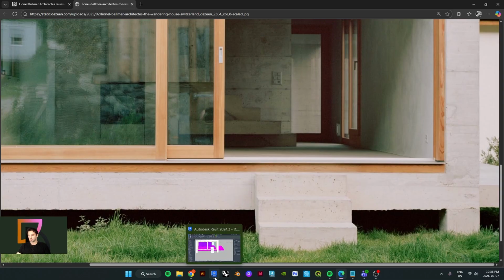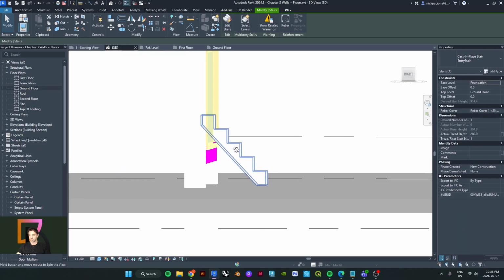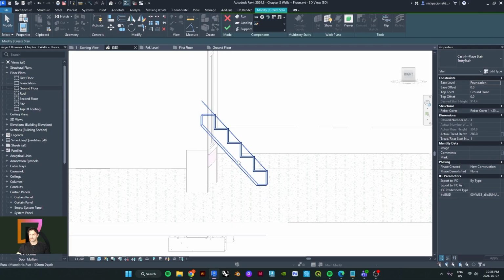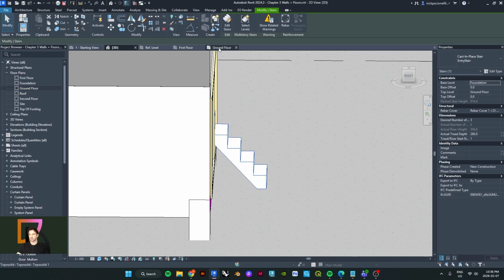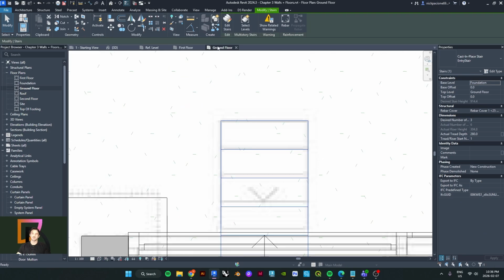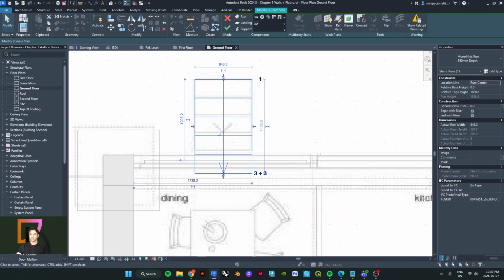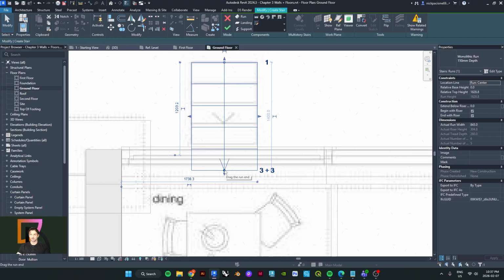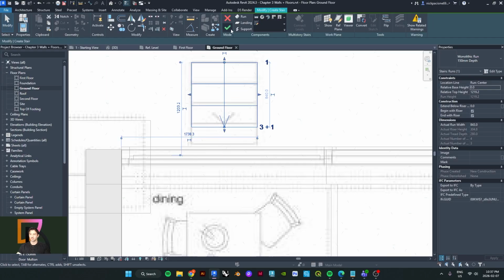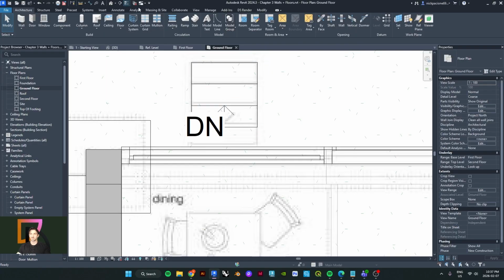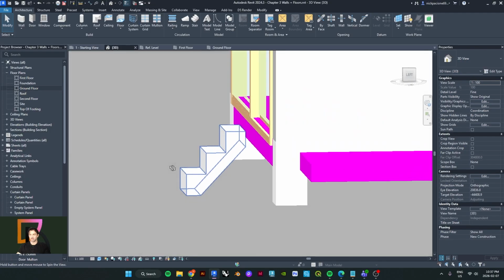What we need to do is cut the stairs off from these two risers. We don't want these two. So I'm gonna edit them, and when you edit the stairs, you can simply pull this back. Now that we have 3, we can hit finish.